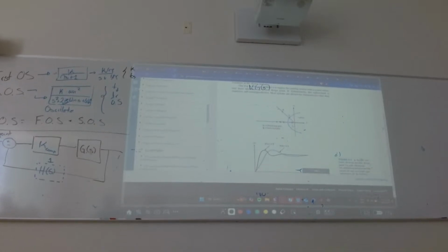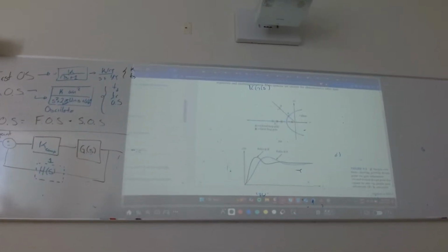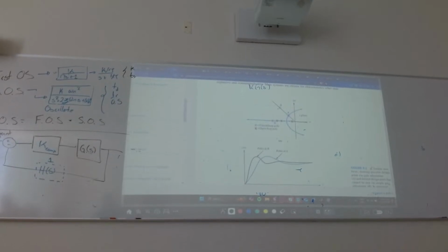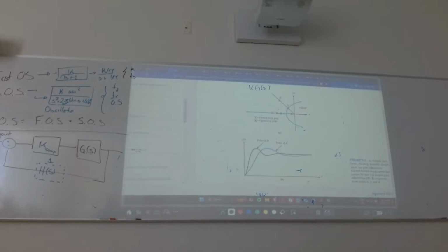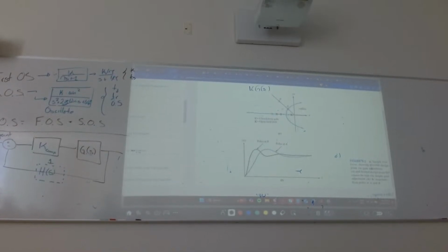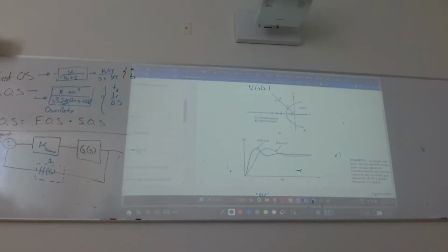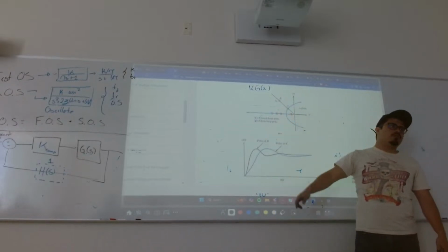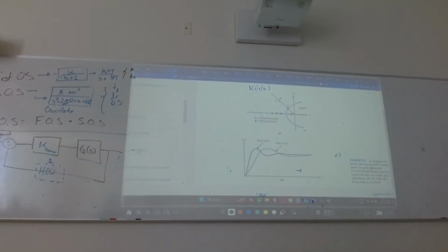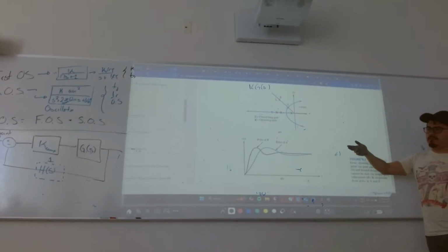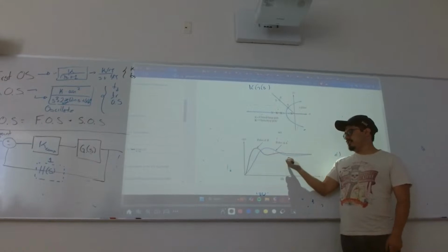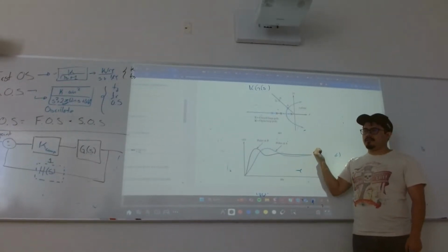As we can see, it says the location of the poles determines the behavior in the time domain, right? So poles at A and poles at B are what are described here. Does that make sense? For example, out of A and B, just by looking at this, you could tell me which is converging faster. The one on the left. So here, the convergence is happening faster, right?